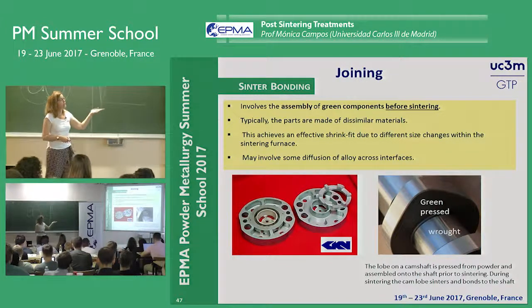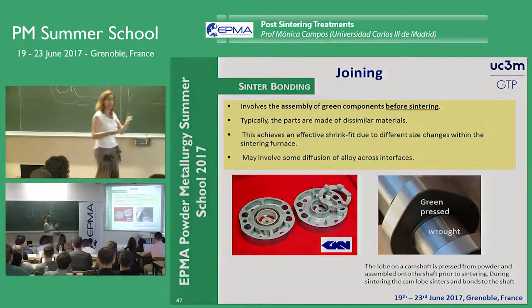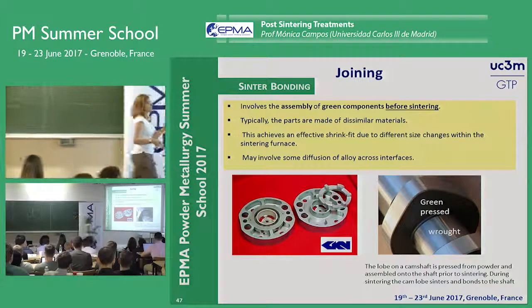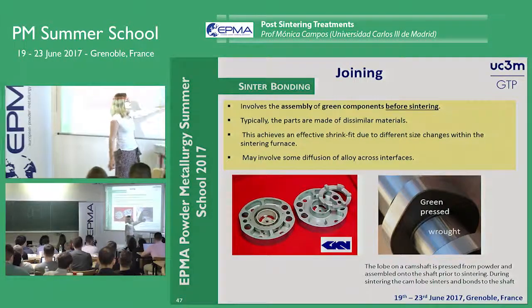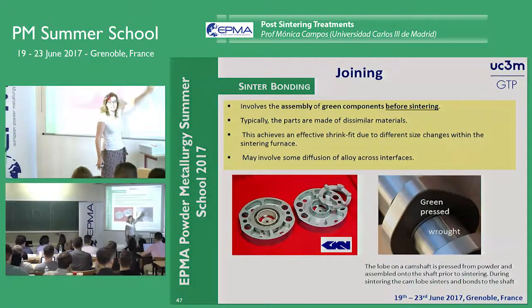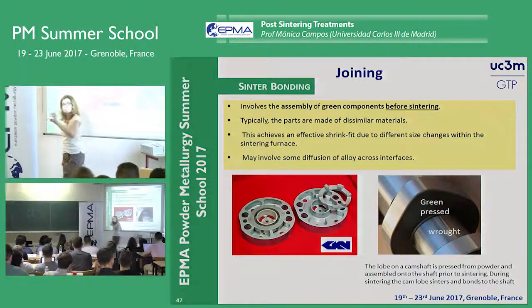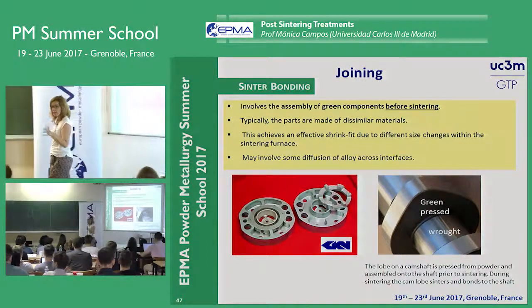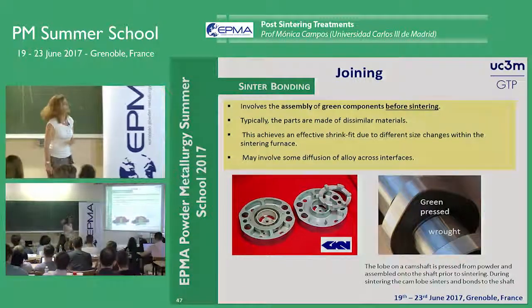In the case of sinter bonding, it is very attractive because we can put together different materials, a wrought steel and a green pressed material, and together we can form the final structure. Very attractive in that case.